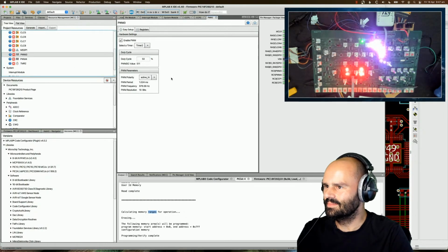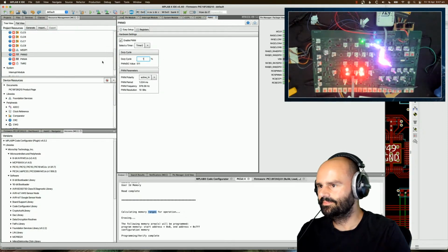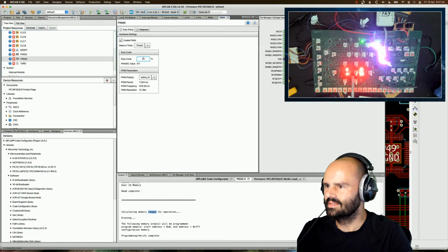And then go down to our pulse width modulation. Now that's interesting. That's got a 50% duty cycle, so I can understand why those were lit up. Let's run this code now, just see if we see any difference in those red LEDs. Do they get a little more dim? No, I can't really notice a change in them. So that's interesting.